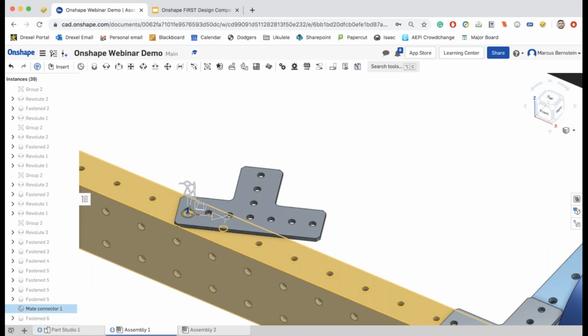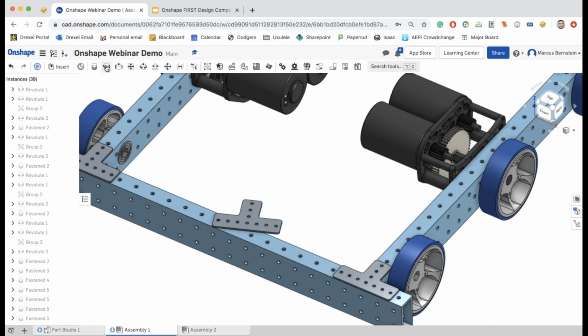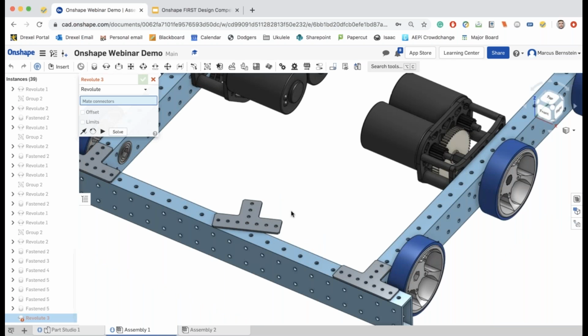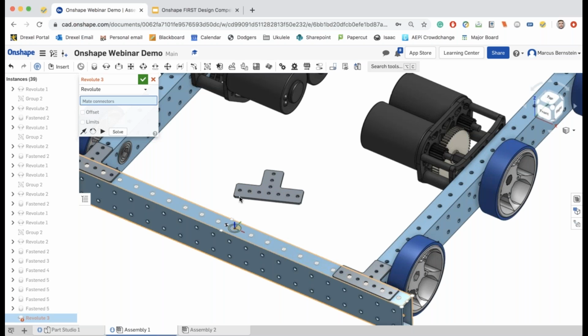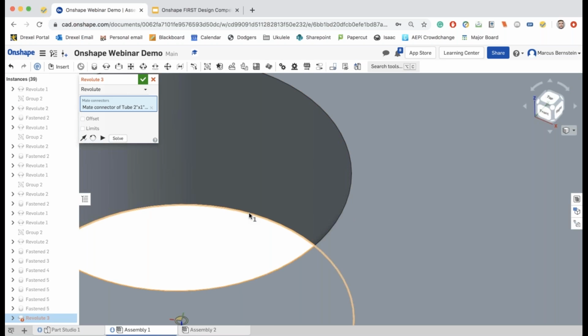There are obviously use cases where you would want to do that. There's a little bit of a different way that you could do it, which is frankly kind of wonky, but it's a totally valid way if this is how you want to do your stuff. And I think it's with the Revolute mate. So what you can do is say I make a Revolute mate with the same, I think I use this hole and this hole right here.